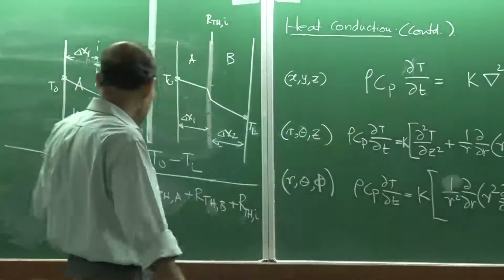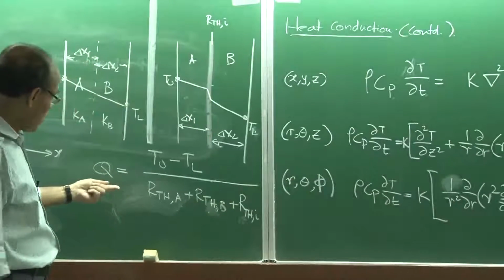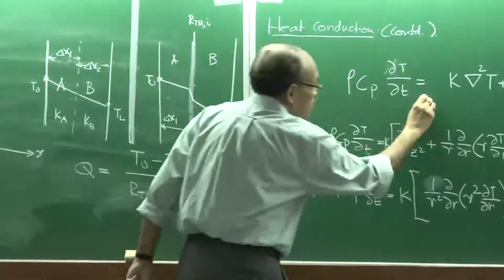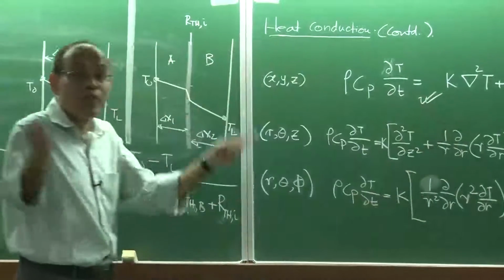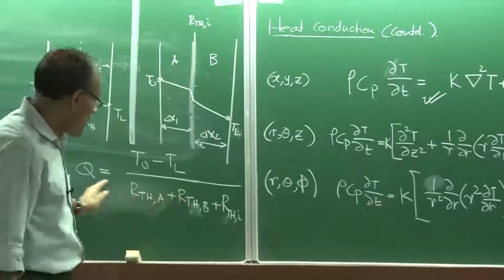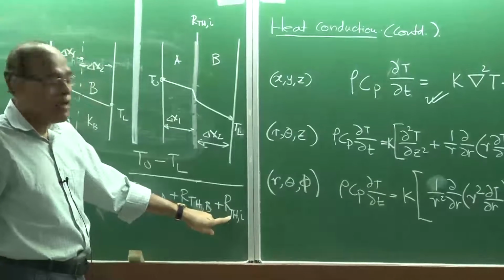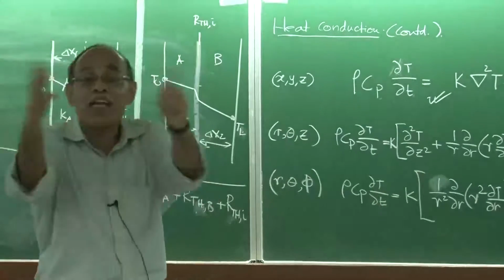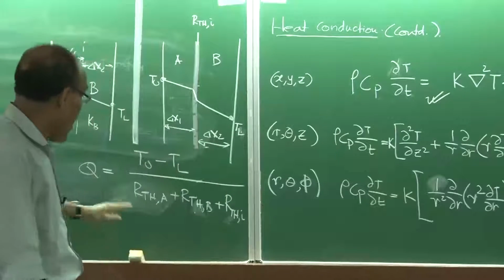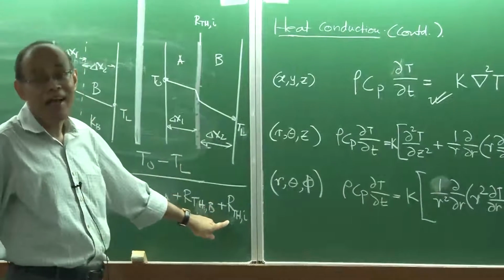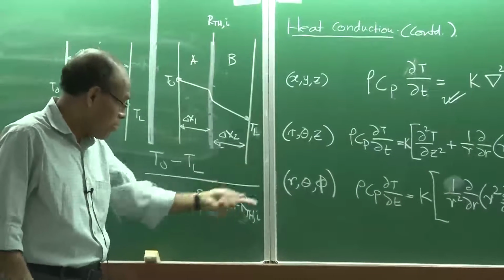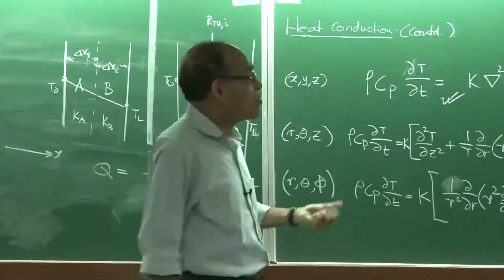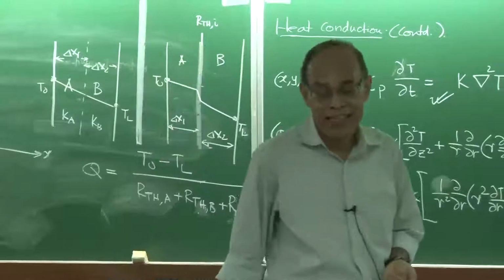The temperature can be calculated, heat flux can be calculated, given the governing equation with the right number of boundary conditions. Introduction of a thermal contact resistance brings in one more uncertainty. So, we become one equation and two unknowns. Therefore, I will demand that the thermal contact resistance has to be determined and given to us. Most of the time, these contact resistances are very important in metallurgical problems.